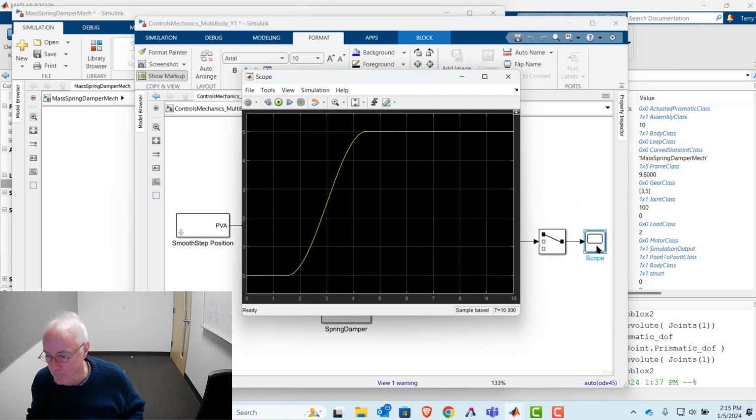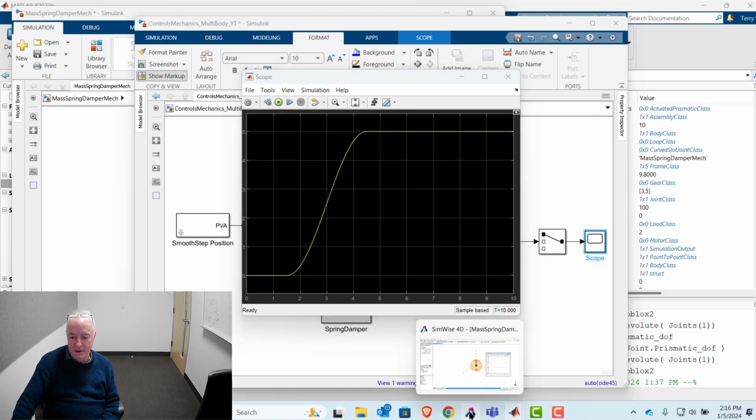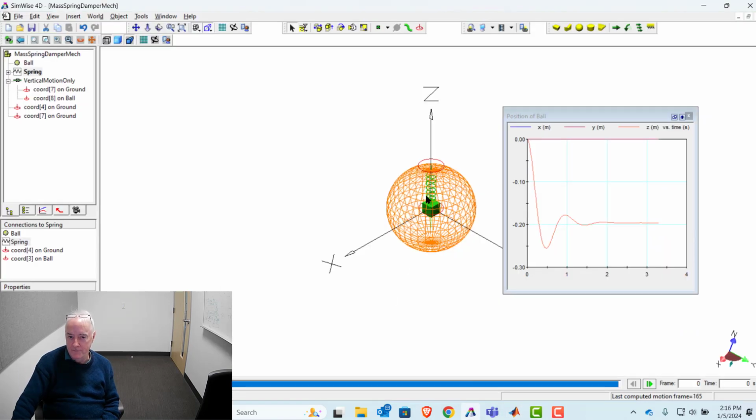I think I'll wrap up the video right there then. That last little thing I went through points to the idea that you're defining mechanics in two different locations, and there's a very wise best practice that simulation people like to stick to, which is define your data once and define it all in one place.